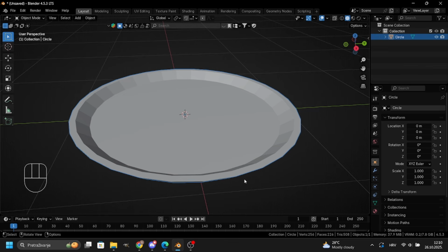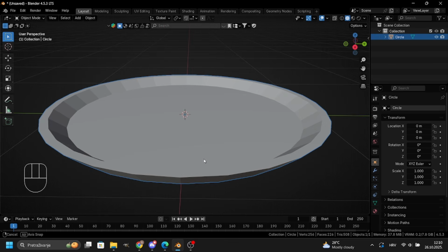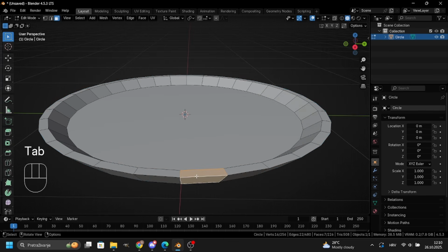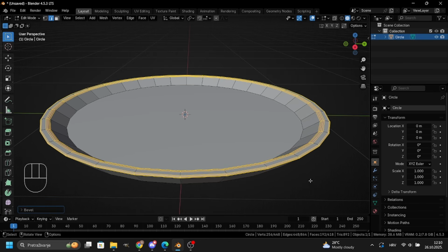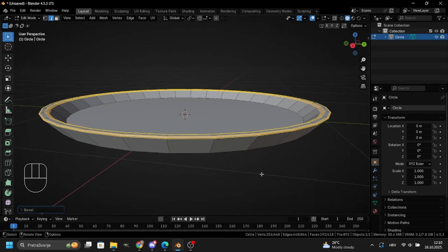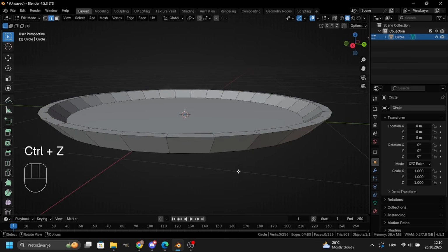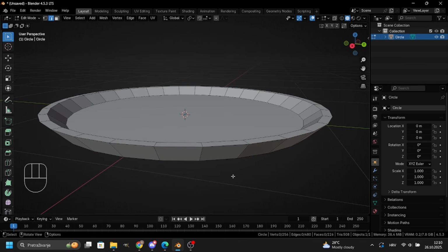We learned about bevels last time. If we want to bevel these edges using the bevel tool or the Ctrl plus B shortcut, we would select the edges and bevel them. After we did that, there is no going back except by using undo. However, if you have made too many steps, you might not be able to undo that action, leaving you stuck with the bevel. In that case, you would have to start modeling from scratch if that wasn't the result you wanted.